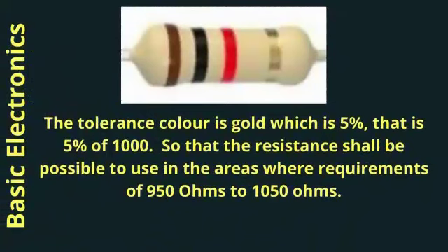The tolerance color is gold, which is 5% of 1000. So the resistance shall be possible to use in the area's needs, 950 ohms to 1050 ohms.